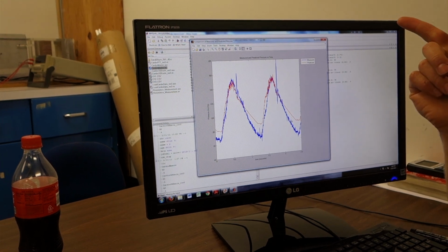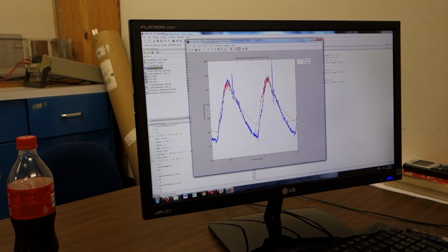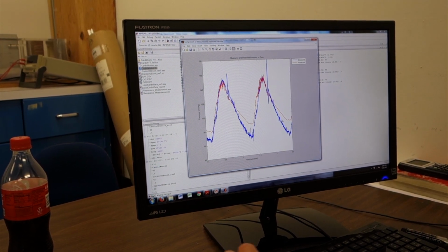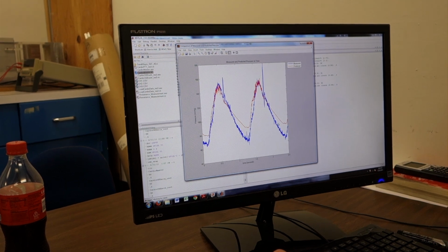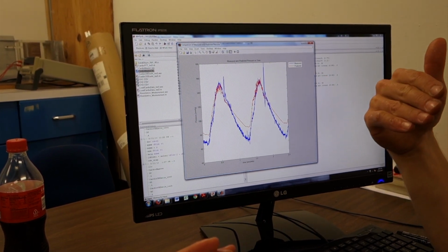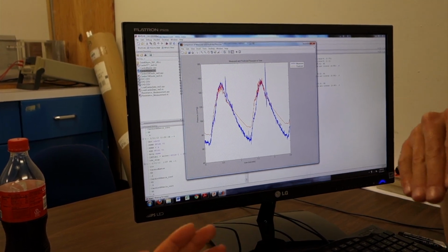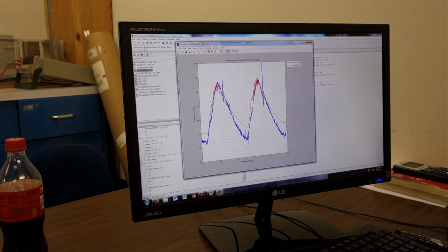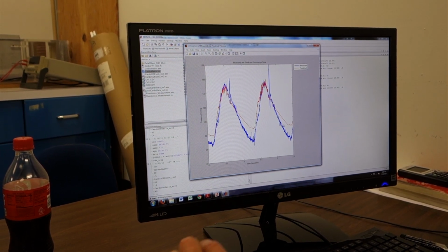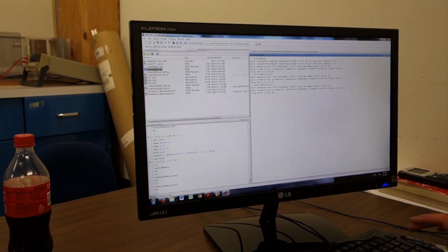Remember, the amplitude is going to be a function of how much on our filter we're cutting off. So we have a low pass filter, and the cutoff frequency affects how much of the input signal is being lopped off. And if I have lopped off too much, it means my cutoff frequency is too low because I haven't been letting enough through my filter. So to make my cutoff frequency higher, remember it's equal to 1 over 2 pi R2 times C, I can decrease C. So I can try to decrease C a little bit.